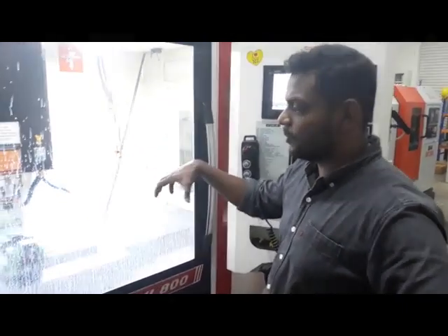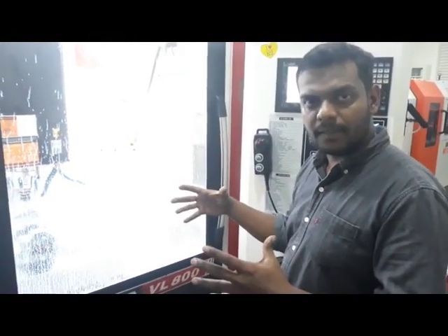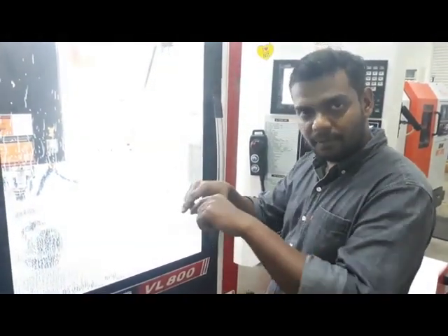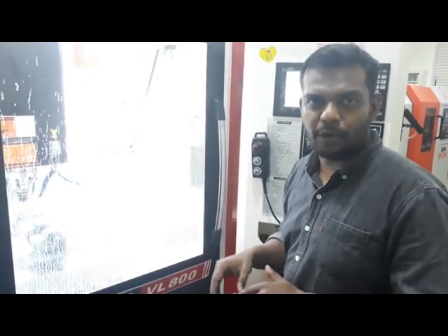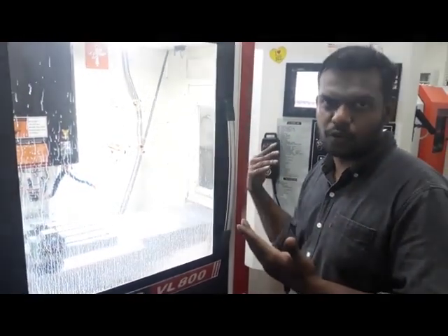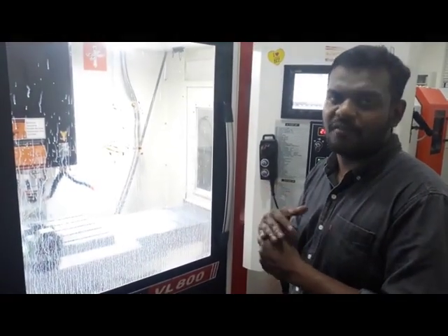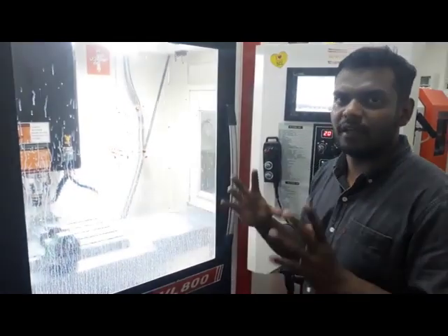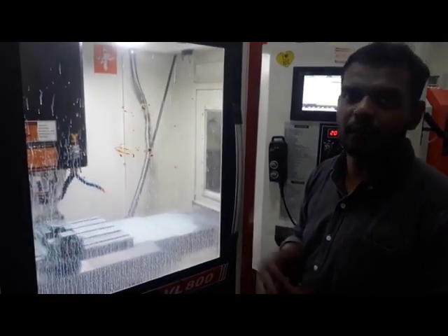So it's taking out the material from the outside, and then the next pass is going to machine the part which is inside the profile that I really want, the 0.2 mm stock. After that, we will go into machining the finishing pass, where the 0.2 mm of stock will be removed, and you get a really good finish out of it.